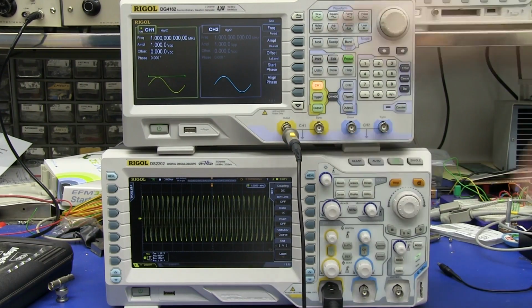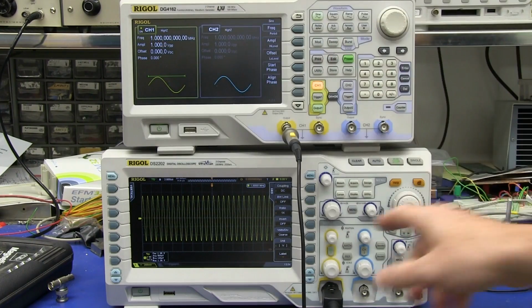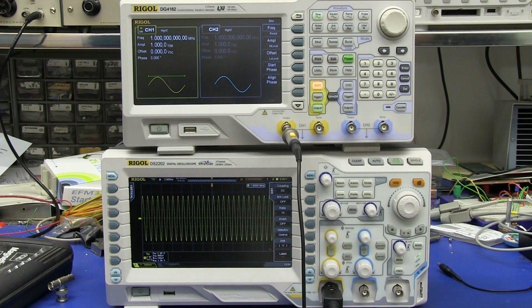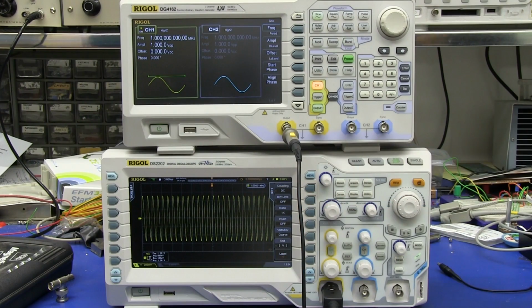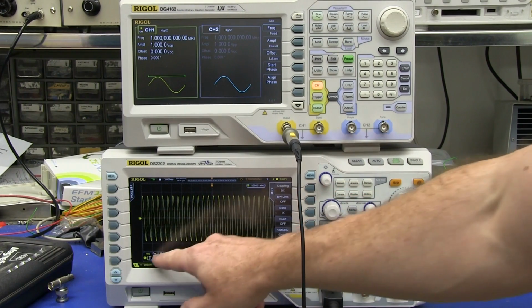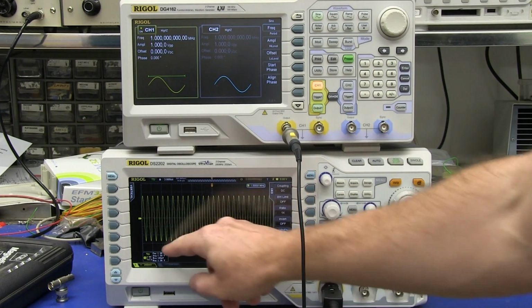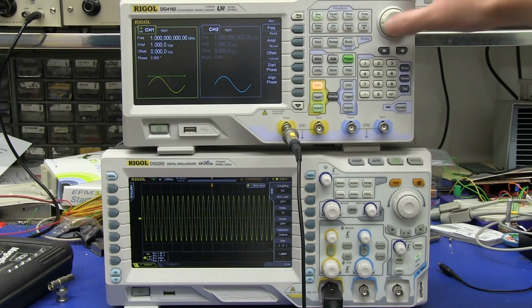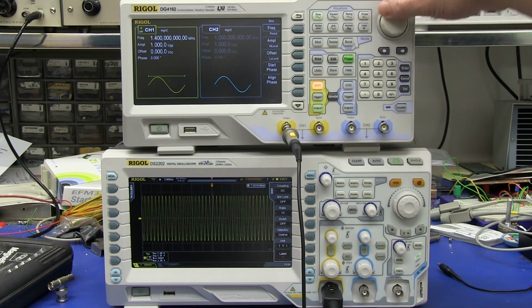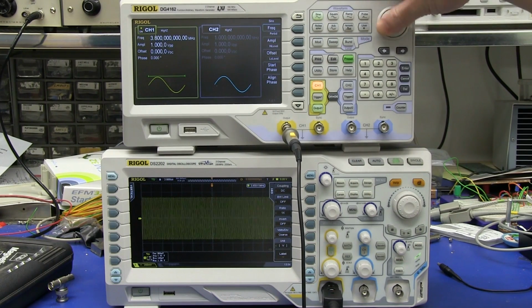So we're on ×1. Let's actually adjust the frequency here up and see if we do get that rated 8 megahertz bandwidth. Because we're at 1 volt peak to peak, and it's specified typically at the -3 dB bandwidth, which should be 0.707, if it's 1 volt peak to peak, it should be 0.707 volts. Let's say 0.7 volts peak to peak. So here we go. We'll wind the frequency up. 2 megahertz, 3. Aha, you can see the amplitude dropping. Look at that.